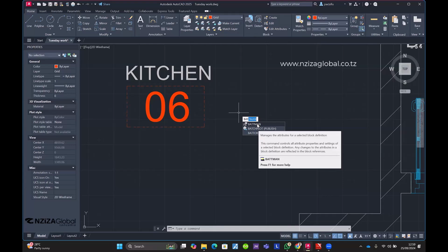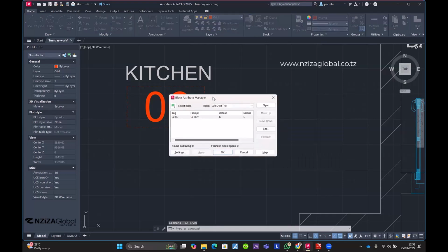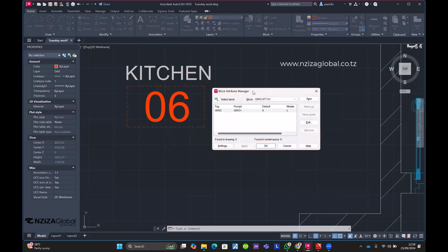Need to type the BATTMAN for the attribute manager. Then we click enter. So now this will bring all the attributes that we have. We select one. You can select one, then click OK.